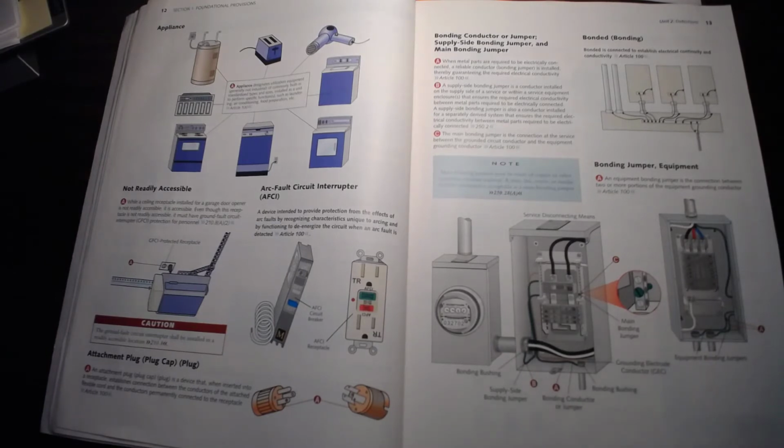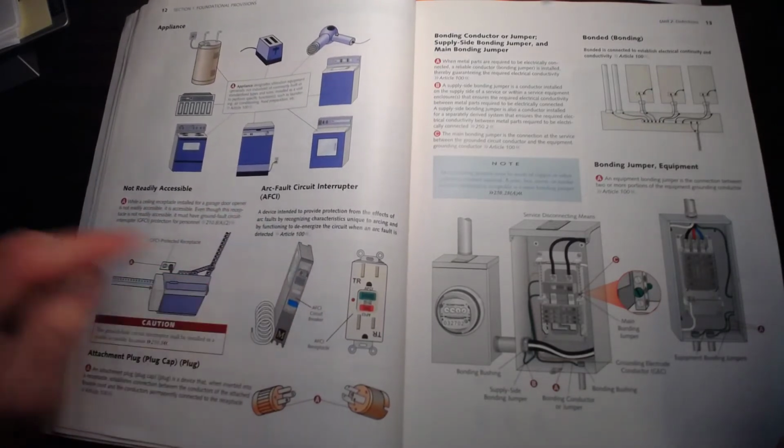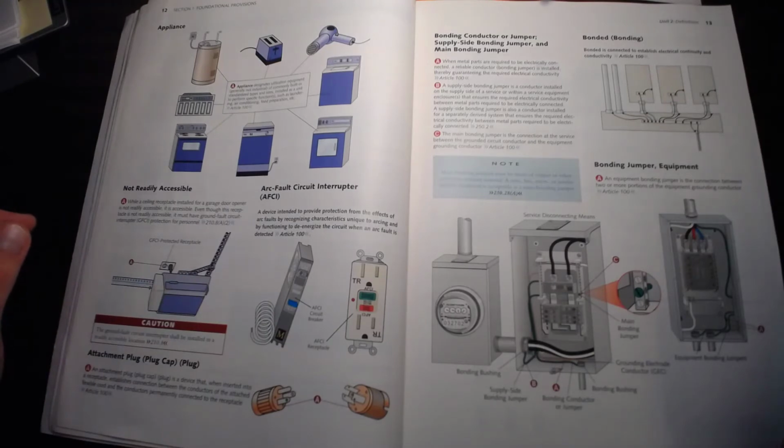The arcing event is being monitored on a PC board, a circuit board inside of the circuit breaker, and that is going to open the breaker up when a non-sinusoidal waveform is detected, meaning that there's a sharp rise in the voltage, causing that transient type voltage. That distortion that comes when arcing is a frequency. So that's why these are very specific in how they are made and what they're for.